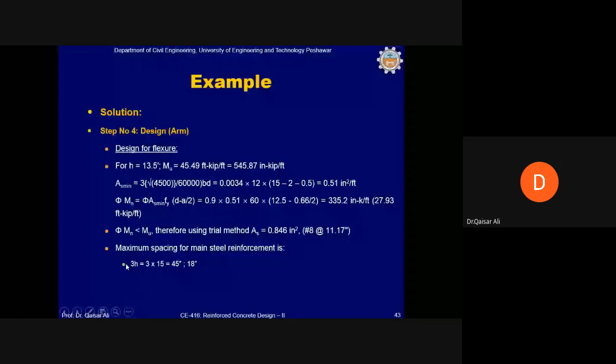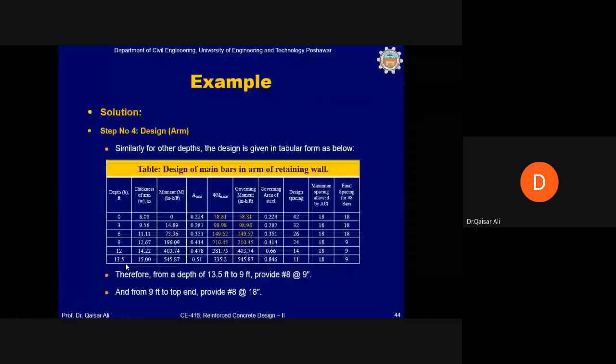Because the bending moment will change along the height of the retaining wall, it is advisable to use different spacing of the vertical reinforcement in order to make the retaining wall economical. In most cases, the reinforcement is changed from the mid height of the retaining wall, or in some cases it is changed in three. The reinforcement is provided in 3 different stages.